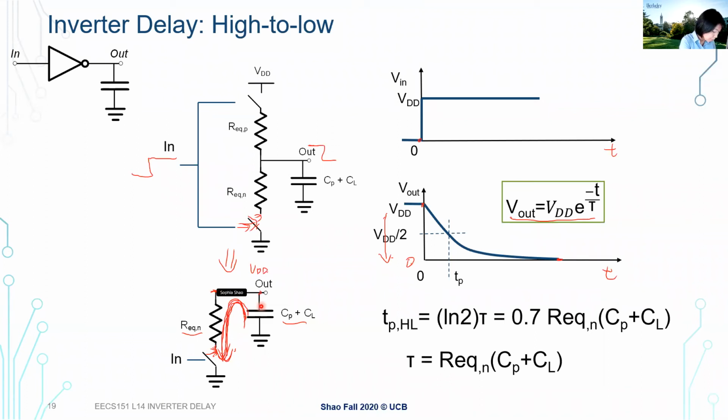We talked about Ohm's law earlier, so look at the current flowing through my resistor. It's basically VDD divided by the resistance. That's the highest current that I can achieve. Over time, as I discharge, the voltage at the node goes down. At the very beginning I discharge really quickly because I have a high current. Then as my voltage goes down, my current also goes down, so I discharge a little more slowly. This is the exponential decay curve that we're observing.